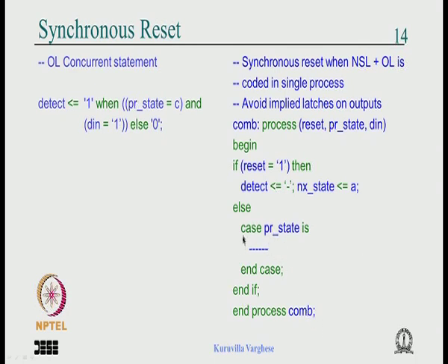But mind you, as far as if is concerned, there is one choice here and a mutually exclusive choice here. Underneath the case the output is specified and here it is not specified, so you get an implied latch for reset equal to 1. It is dangerous, so we have to say the output is some value.